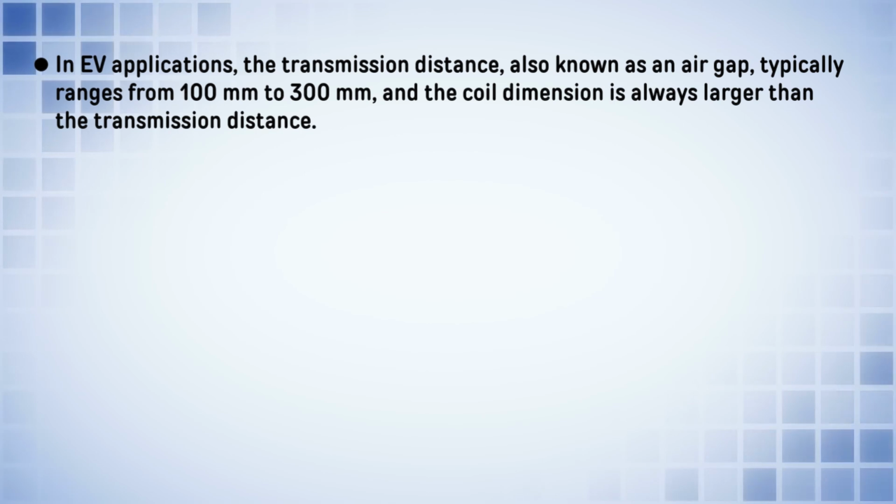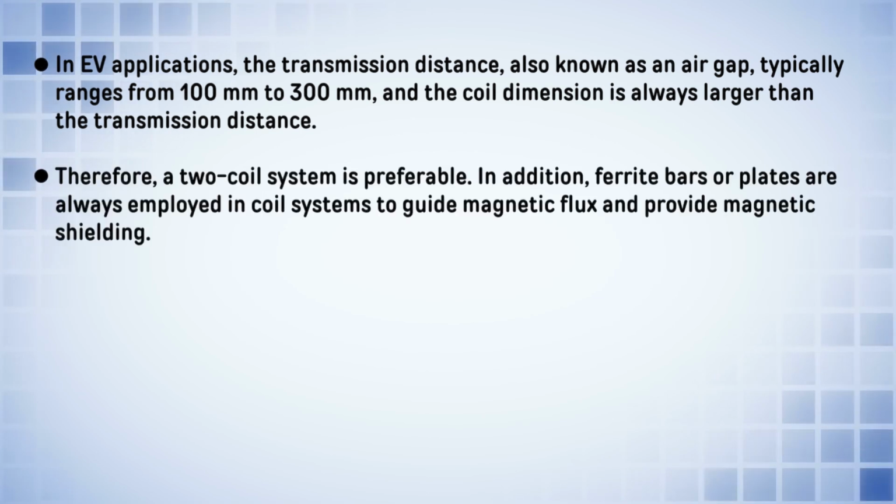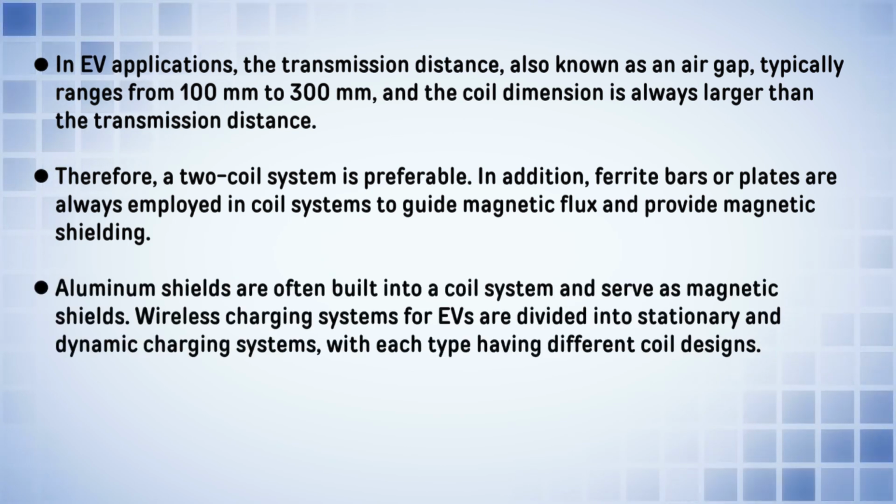am switching the device, so I square all losses will take place during the on state, and when I apply the off pulse to the converter, then again the device will switch from on state to off state, and there will be some losses. To minimize these hard switching losses, people are going for soft switching based schemes, and they are categorized as zero voltage and zero current switching.